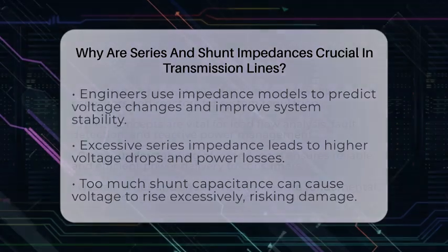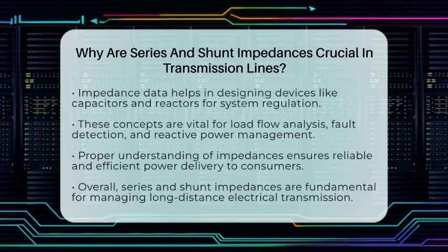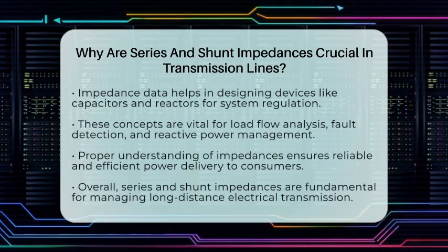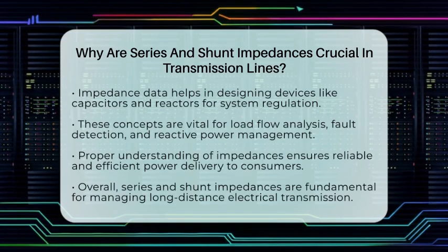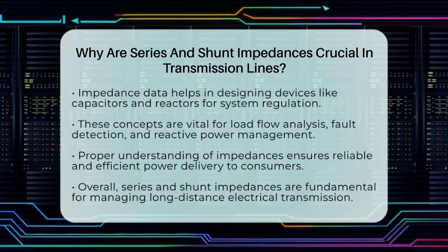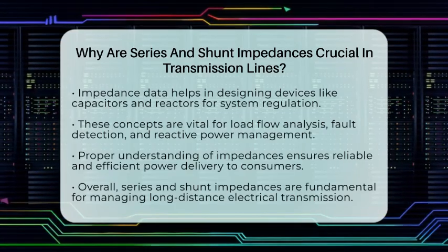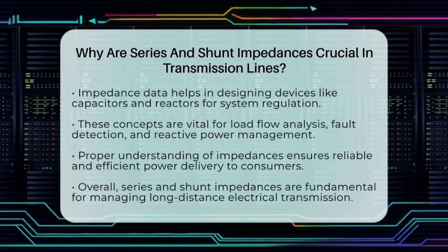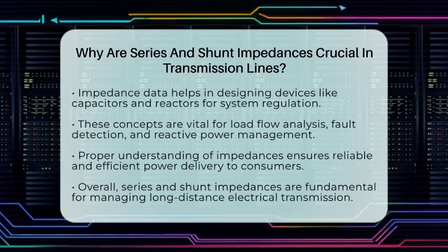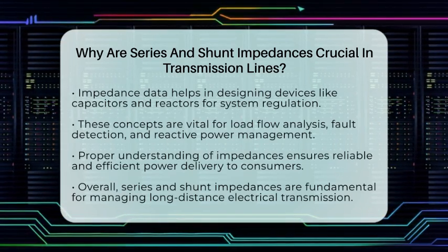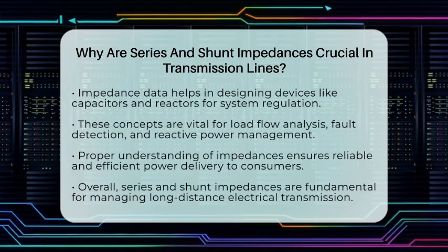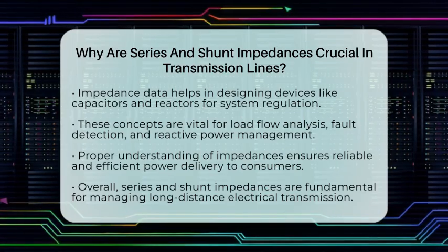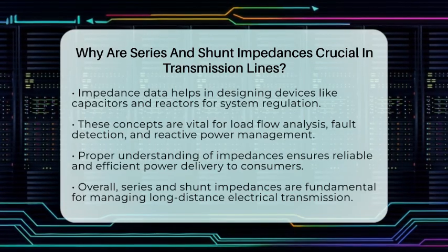In practical terms, models of transmission lines include the series impedance, representing the resistance and inductance, and the shunt admittance to account for capacitance and leakage. These models are used in load flow studies, fault analysis, and reactive power planning. They help ensure the power reaches homes and businesses reliably and safely.